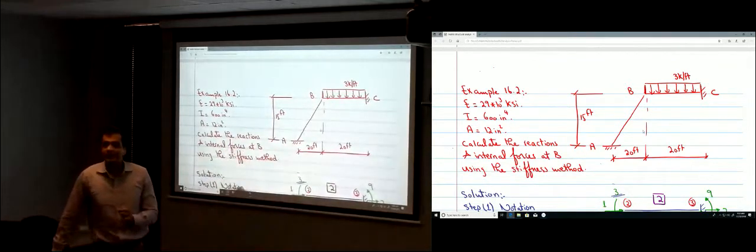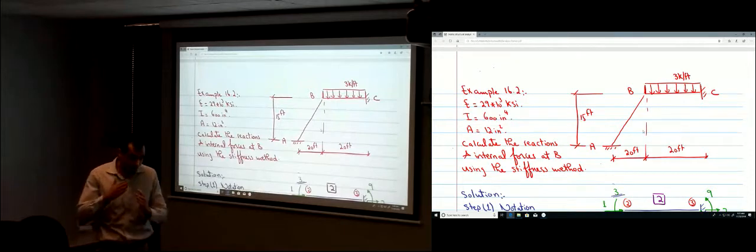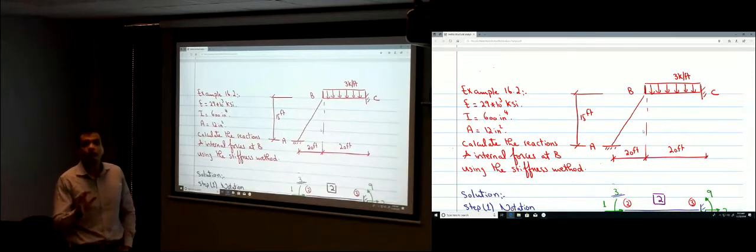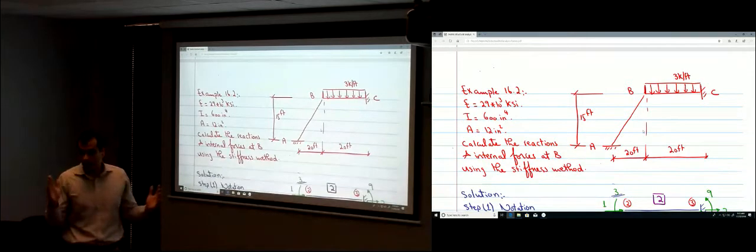What does this mean? It means that the internal forces are a local property. It depends on the direction of the member. It's not the vertical and the horizontal force. It's the force perpendicular to the direction of the member and in the direction of the member. So it is the local forces. To find the internal forces, you would find them from the equation P equals KU, but you have to use the equation in the local direction, not in the global direction, for each of those members separately. Is this point clear?